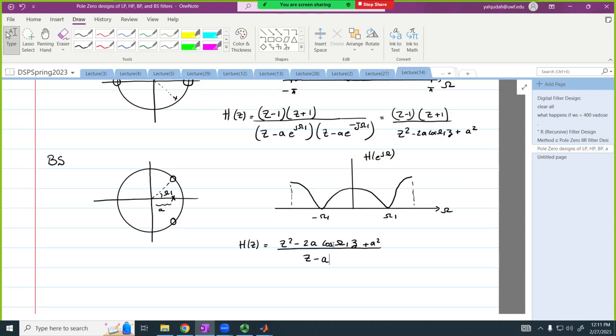Because we're designing an IIR filter. If I remove this from here, then I'm going to be getting an FIR filter. Does that make sense? Later on, we'll see the FIR filter. We'll do something like this without any denominator. And somebody is going to ask, why is there no denominator in here? What will the answer be? It's finite. Because it's an FIR filter.